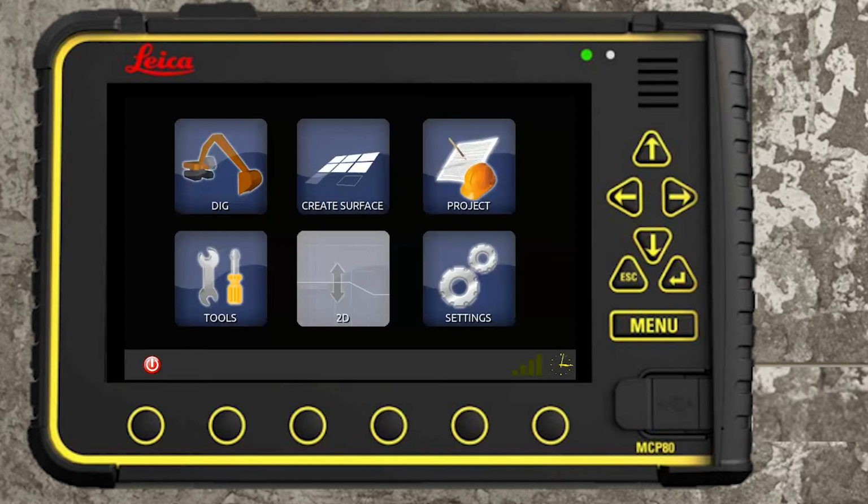So it's handy in that sense, instead of having to have lads mark out on the ground or whatever, that there are services buried. You can have it on your 3D system on the panel itself. With the avoidance zone, it's not something that's created on the machine control system. So you would have to bring in the file and then set it as an avoidance zone.